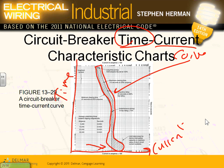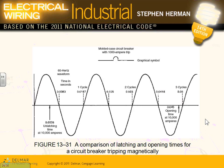Today, guys, we're using the SKM software I downloaded on your machine. That's what you're going to be looking at. If you don't understand what this curve is, good luck doing the coordination. You have no idea what the coordination is. This coordination will transfer into data that you give to the electrician with a screwdriver, to go to the face of the circuit breakers and set them at the right settings. That's what this translates to. Big deal in the high voltage.